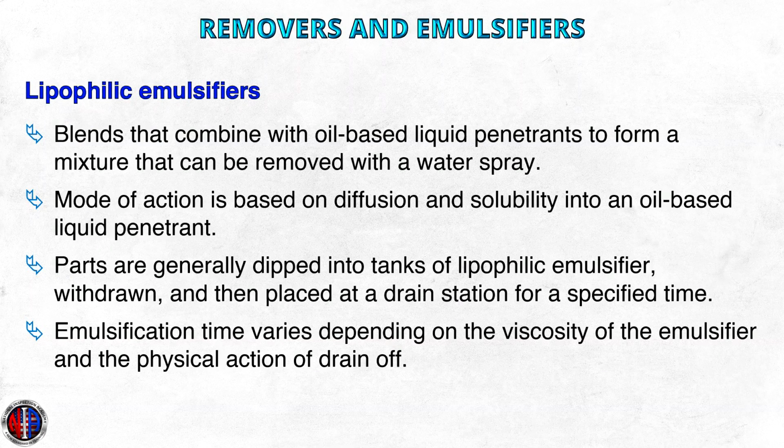Removers and emulsifiers. Lipophilic emulsifiers. Lipophilic emulsifiers are composed of liquid blends that combine with oil-based liquid penetrants to form a mixture that can be removed with a water spray. Their mode of action is based primarily on diffusion and solubility into an oil-based liquid penetrant. Parts are generally dipped into tanks of lipophilic emulsifier, withdrawn, and then placed at a drain station for a specified time. The emulsification time varies depending on the viscosity of the emulsifier and the physical action of drain-off. Therefore, it is important to control the emulsification time to prevent over-emulsification of the liquid penetrant in the discontinuity.